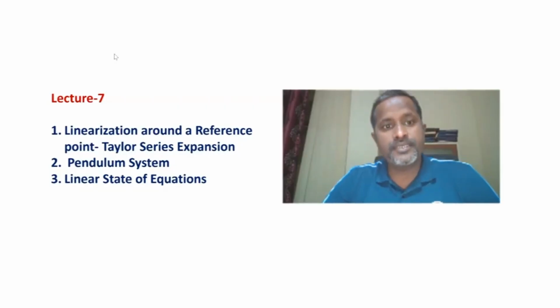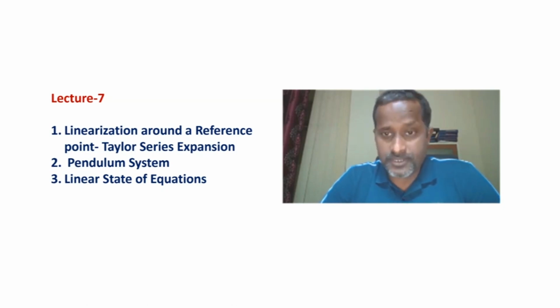In this lecture, we'll be discussing the standard method of linearization around a reference point through the Taylor series expansion. Then we'll apply this concept to the pendulum system and see how we can get two different models of linear state equations of the pendulum system. The linear state equation that we find in this lecture we can validate against the findings of the previous lecture. Then we'll conclude the lecture.